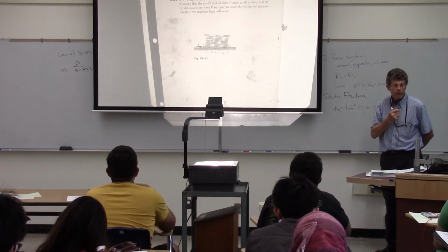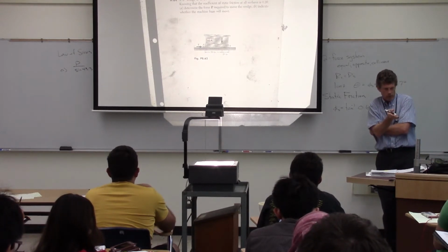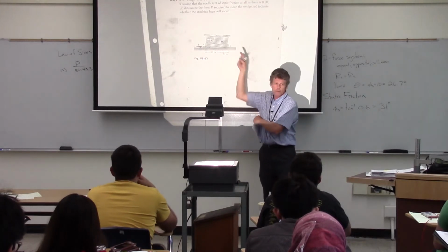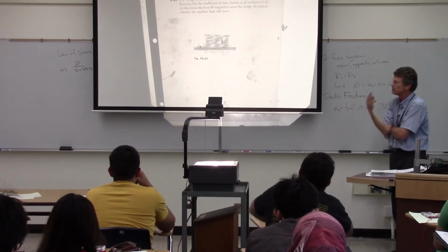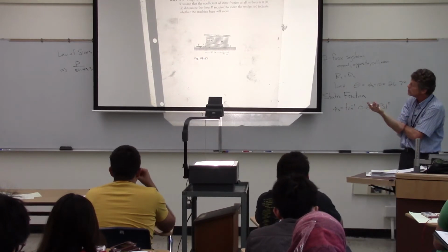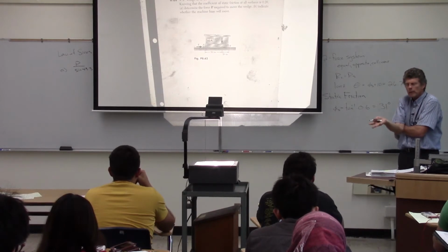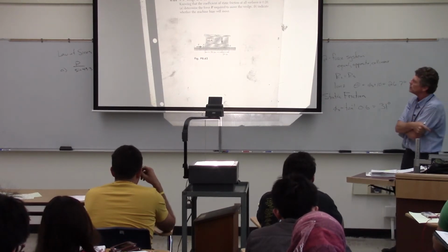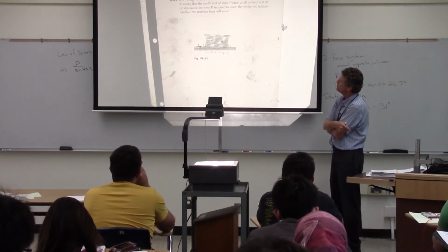So, it's almost like a pin joint, kind of. We want it to behave like a pin joint. Yeah. And the problem is that because it's not truly fixed there, it could move. So that's why we generally in friction problems have to do a two-step process, or at least in wedge problems. You're going to be pushing something, and then oftentimes you've got to check to make sure that the rest of the body doesn't start moving off too.